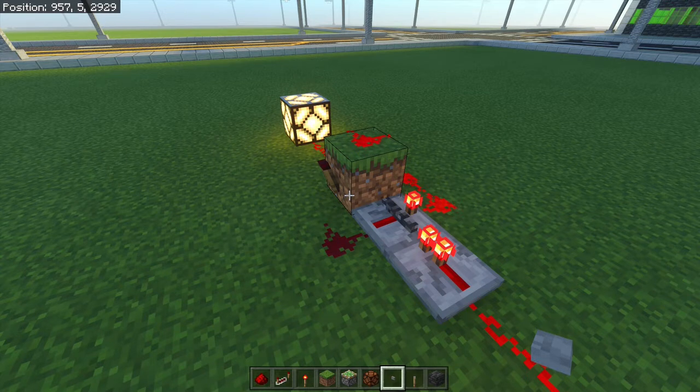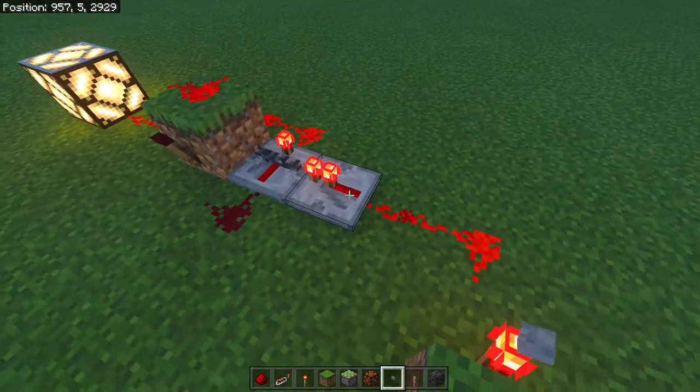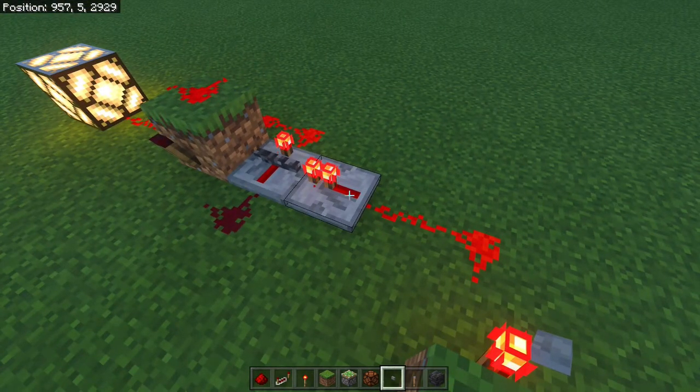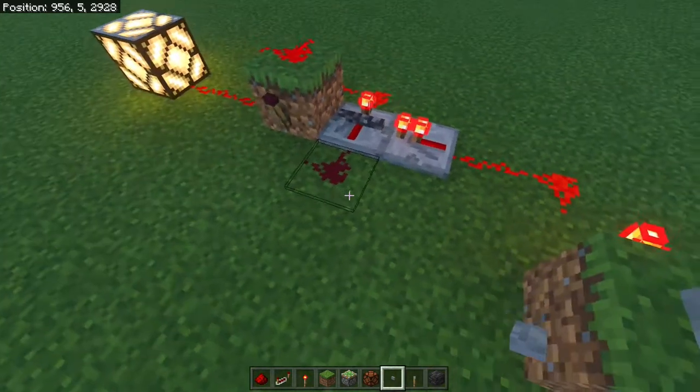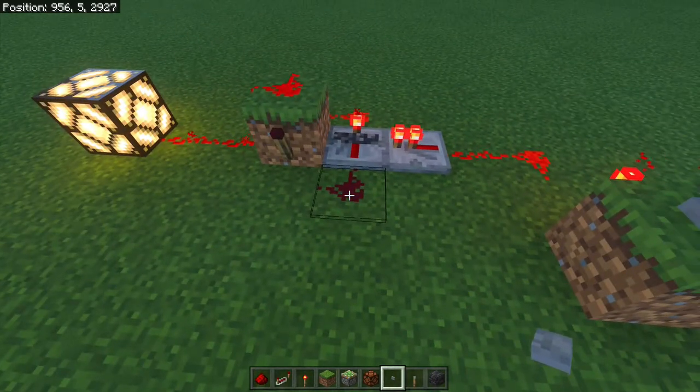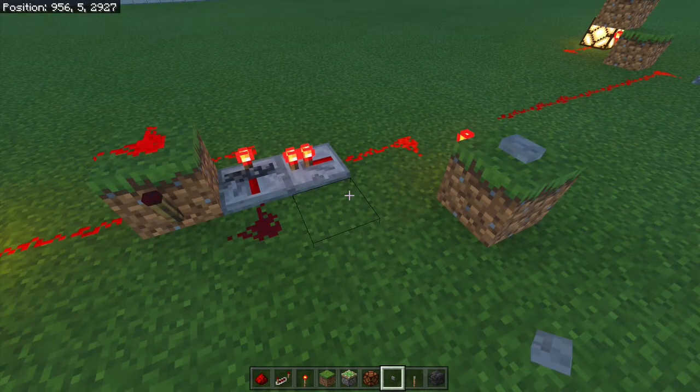But this circuit is kind of a useful little component called a T-latch in circuit design, or a T flip-flop. The T stands for toggle. And the idea is that it's actually a memory circuit that holds a state, and when you clock it, and again I'm sort of overloading this term of clock because it's the way that people who design actual real circuits in real life talk about this thing, when you clock the circuit, it switches states.